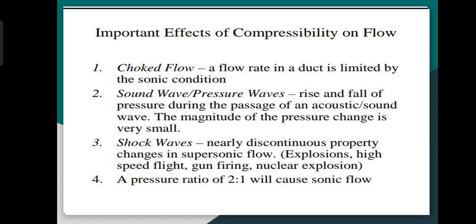Coming to important effects of compressibility on flow, the first one we want to discuss is choked flow. The flow rate in a duct is limited by the sonic condition. Then sound waves are the rise and fall of pressure during the passage of an acoustic wave. The magnitude of the pressure change is very small.